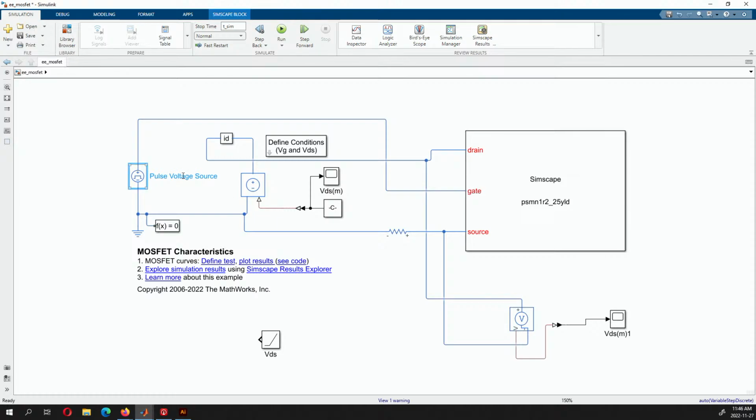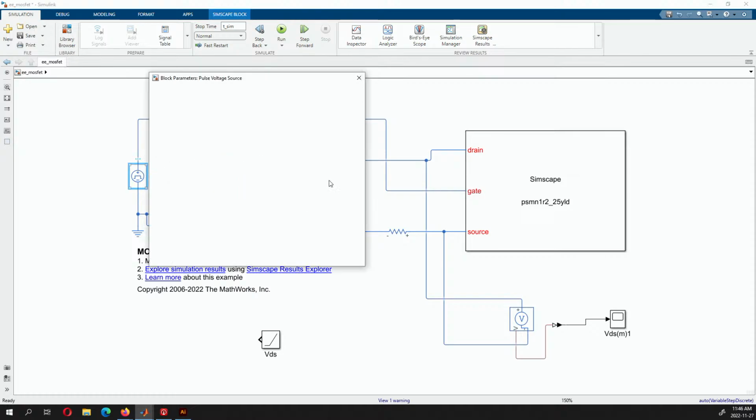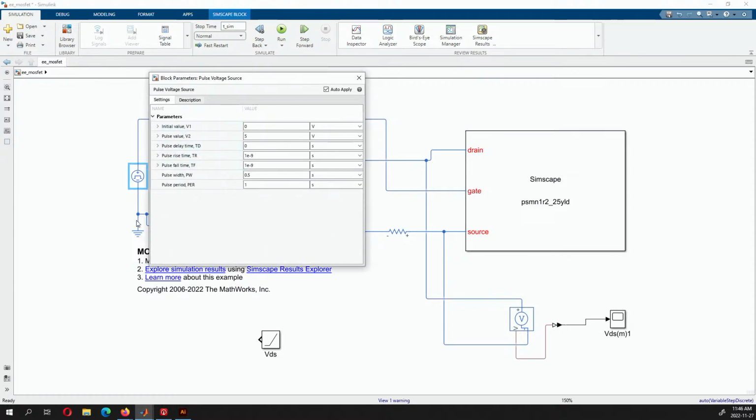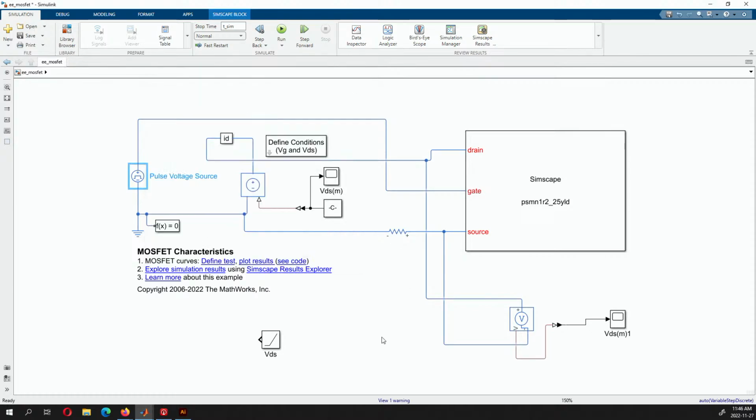So we're basically trying to simulate a switching phenomenon over here. Now mind you, this does not really simulate exactly what the switching speed would be when you're trying to control an electronic speed controller, but just for the sake of this particular demonstration in this video, just to understand the characteristics, I'm making it one second. The switching speed would be at least 10 kilohertz to 20 kilohertz. So that's going to be 1 divided by 20 kilohertz. That's the seconds that we should actually be working with. But in this particular case, I'm just making it generous with the time.